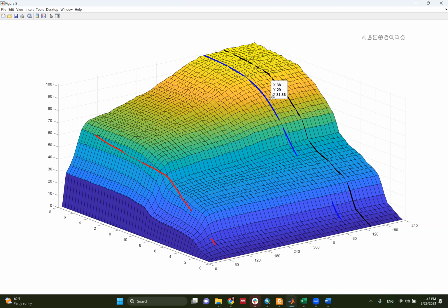So I have a 4D matrix: depth, duration, simulation, and components. First, I compress all the components to get the building and take the mean of the simulations. Then I moved it from a 4D matrix to a 2D matrix, a function of flood depth and flood duration. And for each flood depth and each flood duration, I have the total building loss. And this is the function that I did.